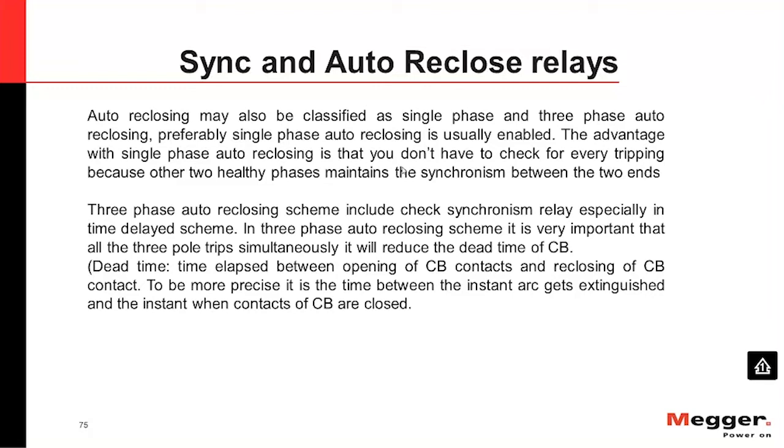In this case, it doesn't need synchronizing because the other 2 phases are already synchronized, so directly it will close the faulty phase. But in case of 3 phase, it requires synchronism relays. And these synchronizing relays, again, we have to go to the same quantities we just talked about: the voltage, the frequency, and the phase angle, which will also affect the auto-recloser time.